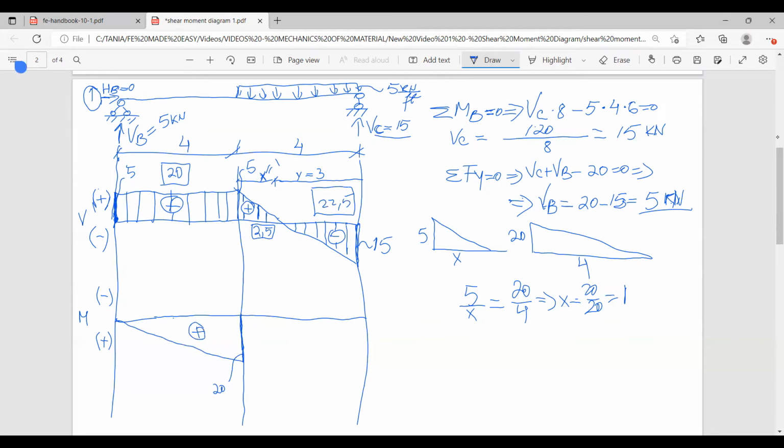And this is positive. And again, if you are used to doing it positive on the top, negative at the bottom, just please do it that way. There's really no difference. So let's continue now. Here, when a shear diagram intersects like this, we actually have to draw a line down, because at this point we're going to have a maximum or a minimum. So let's see. We have 2.5, which is positive, which means we're going to go towards the positive.